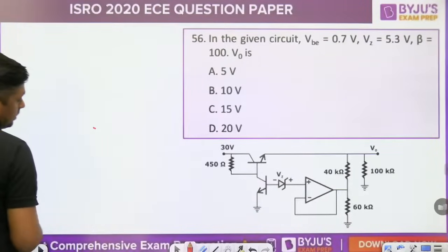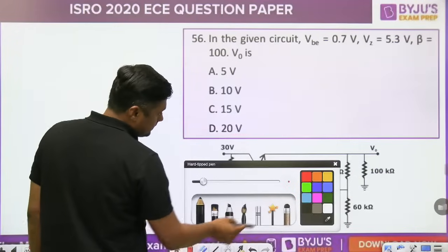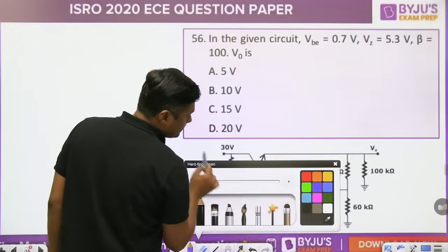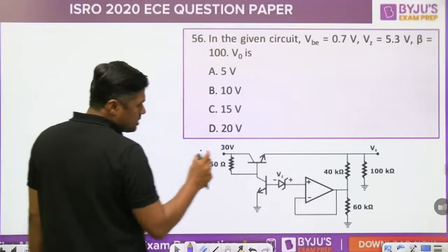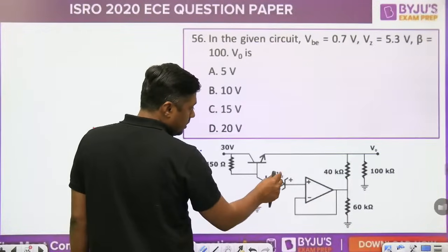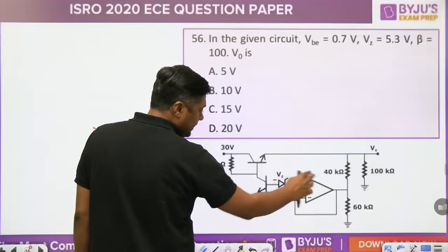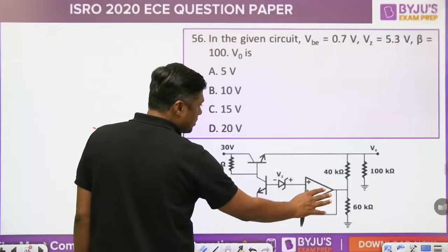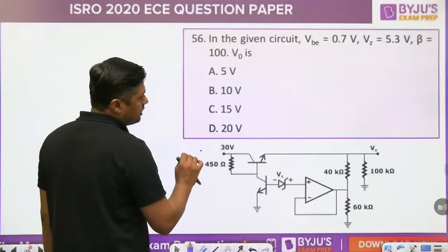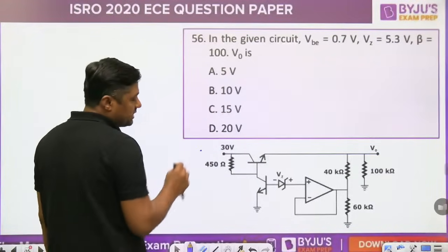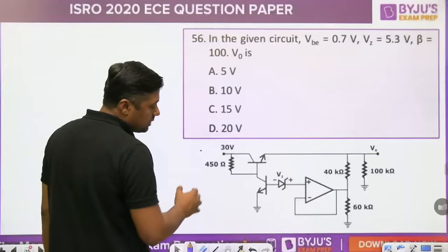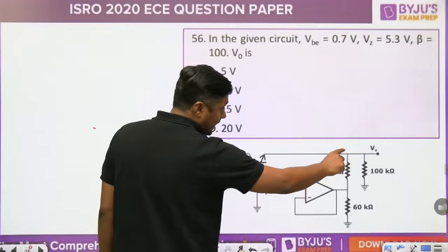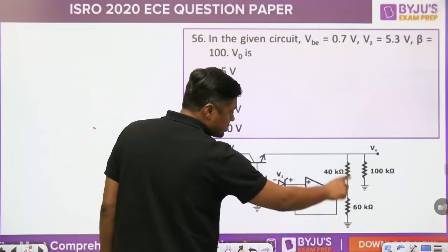It is a question on a voltage regulator. Suppose you want to find the answer, then watch this transistor, and let the current entering the operational amplifier be 0. V0 is asked, so simply focus on that. 30 volt is applied here, a very high voltage, right? All the answers are less than 30 volt, which means the circuit will work properly. This is called unregulated voltage, and that is called regulated voltage. The regulated voltage is the voltage across this branch.